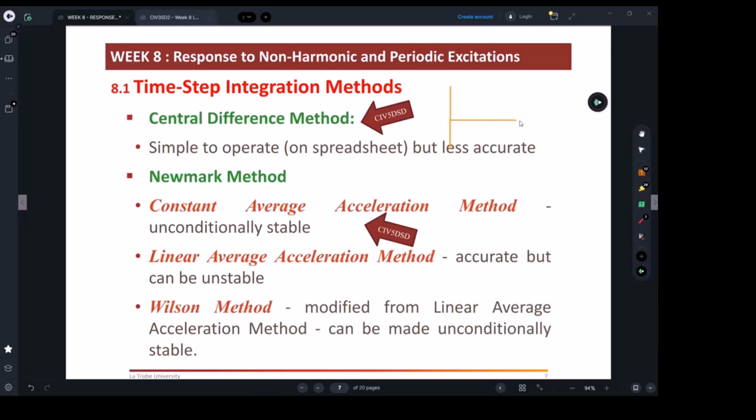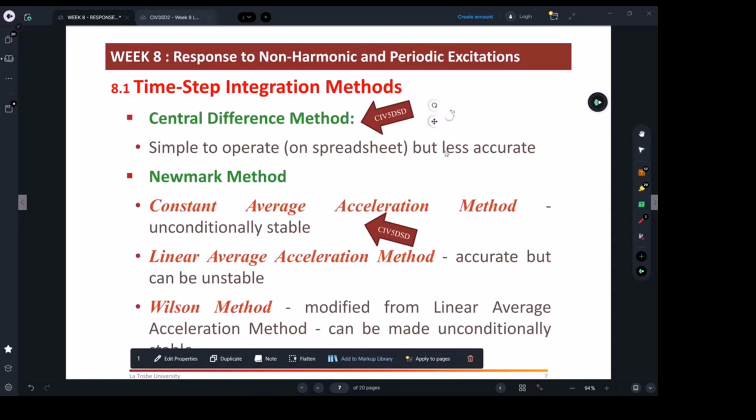So this is the response plot, for example. You may start having your response be like this, just flying, which is because the integration starts blowing up. They call it blowing up results in the textbooks. You're just going to keep adding, but it's because you have missed some of the information from the ground history. So you're no longer giving the right response. Right?